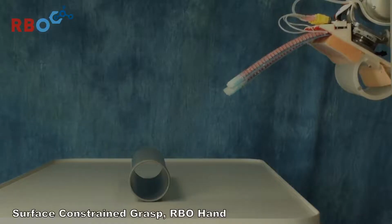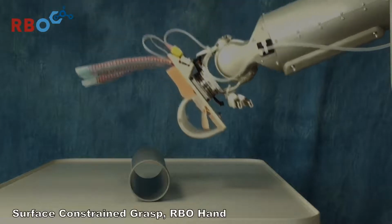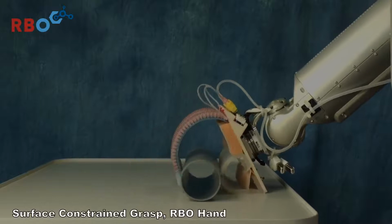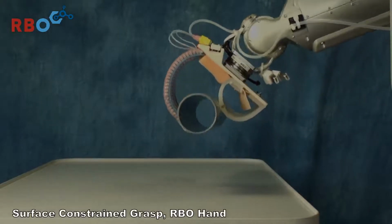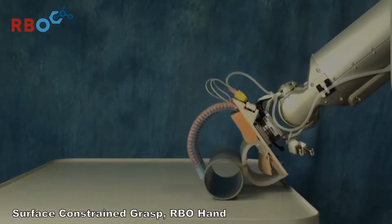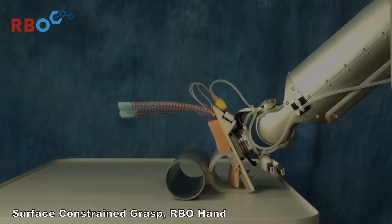The way environmental constraints are exploited may differ from hand to hand. The highly compliant RBO hand can use the table surface to position itself close to the object. Then, by flexing its fingers, the object is pushed against the palmar pad, establishing force closure. Along the way, the table constraint guarantees that the object cannot escape.